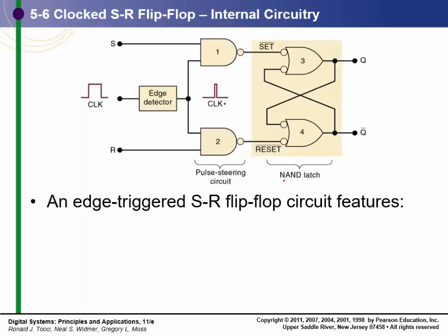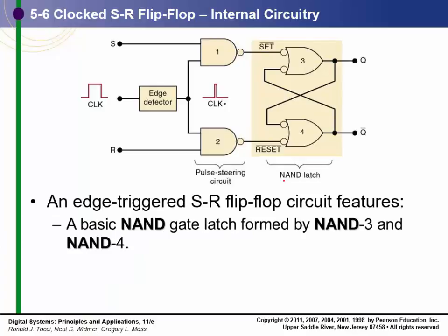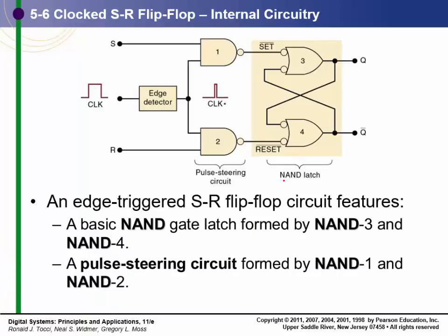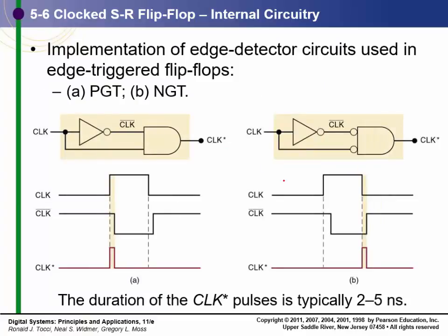I should point out that normally when we call something a flip-flop, it's going to be an edge-triggered device. If we call it a latch, it's usually not clocked. It's not edge triggered. And again, I'm not too worried about the edge trigger.